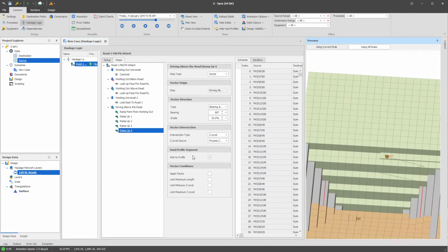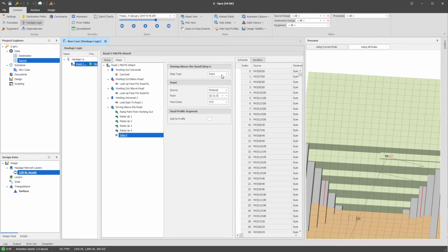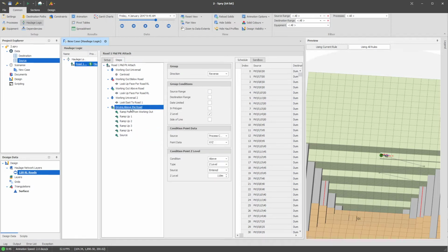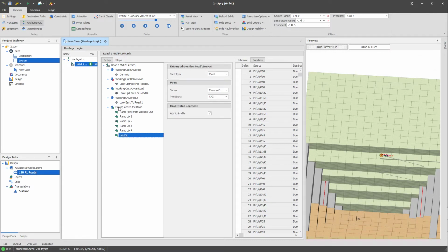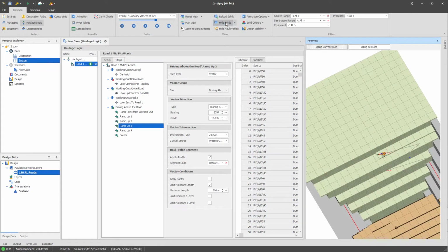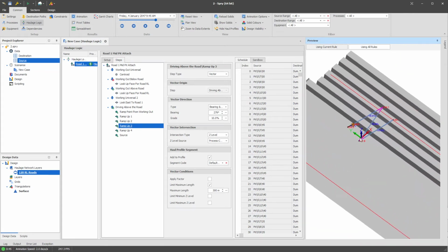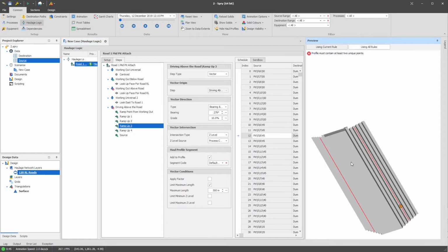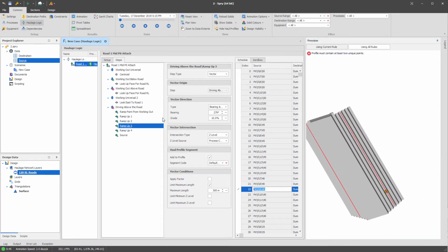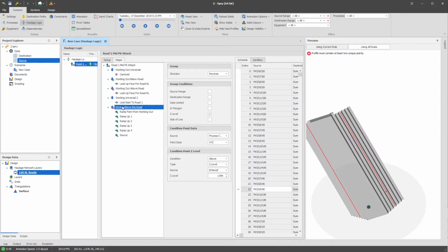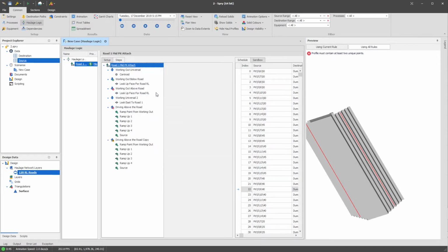But the final thing that I need to do in all of this then is add the drive to the actual centroid. So call this one source, but same thing. So what I do is I'm driving in reverse from the source back towards the road. And if we turn off the solids for a moment, what we're going to find is no matter where we are, oh sorry, this one is driving above the road. We haven't done the below the road, so let's copy that, paste that in as well.